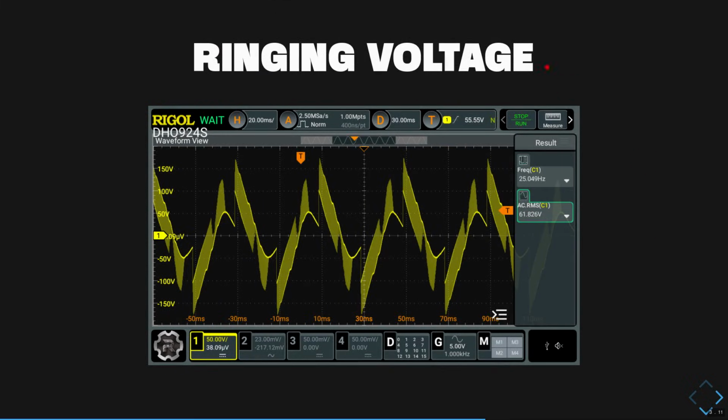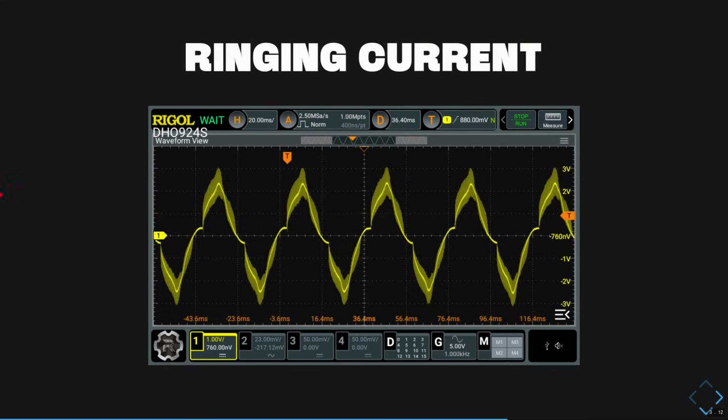All right. So when we look at the ringing voltage that is generated out of this, it honestly looks quite ugly. Technically speaking, from the measurement perspective, the AC voltage is quite high, 60 volts RMS, and the frequency is also well, but the voltage itself looks ugly. But what's more important is the current. This is also measured against a shunt resistor here, and it is not perfectly sine shaped, but good enough. And most importantly, the bell or the ringer rings quite loudly with that approach.